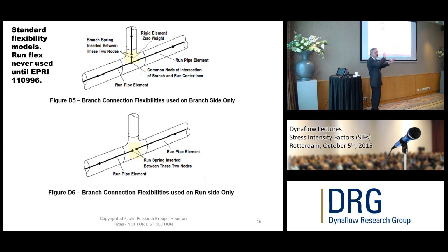What happens is if you've got pump manifolds where you've got multiple inlets to a large manifold that comes in, the manifold is very soft in torsion because of all the holes that are cut in. Well, we never see that today. But this flexibility factor in the torsional direction helps you with that. It gives you the flexibility property.